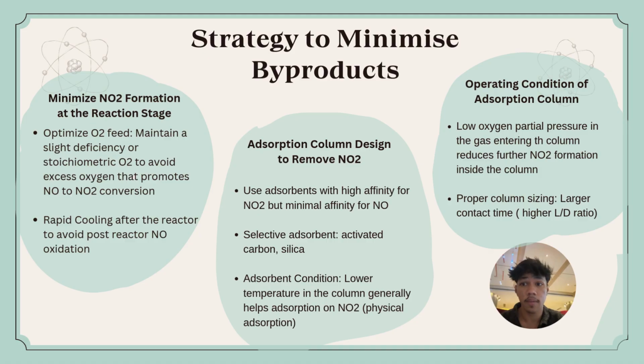In our case, we use activated carbon and silica as adsorbents. And also, for the adsorption conditions, we can use a lower temperature in the column. Generally, this will help adsorption of NO2, which will diffuse and be adsorbed, so more NO2 will be removed in this case.